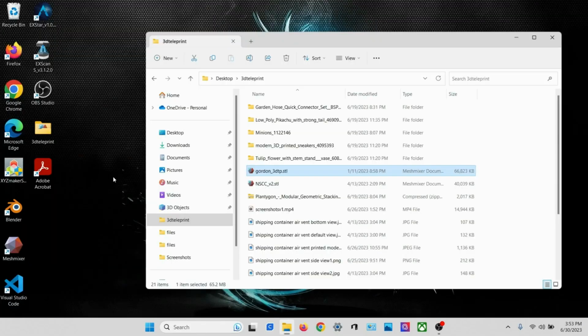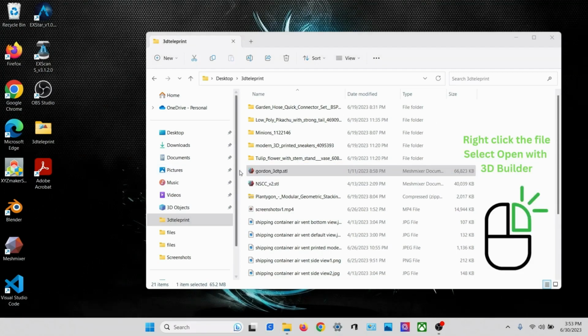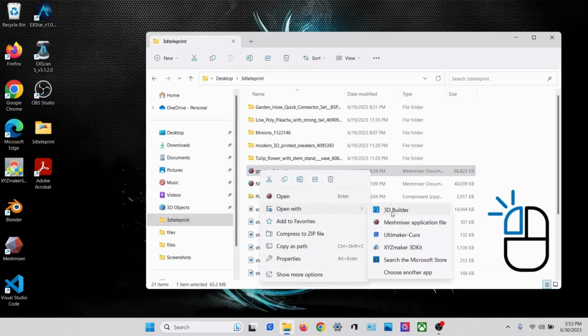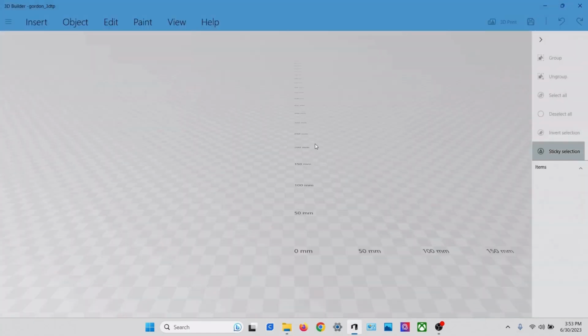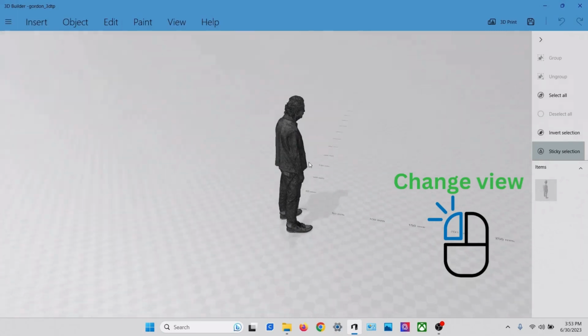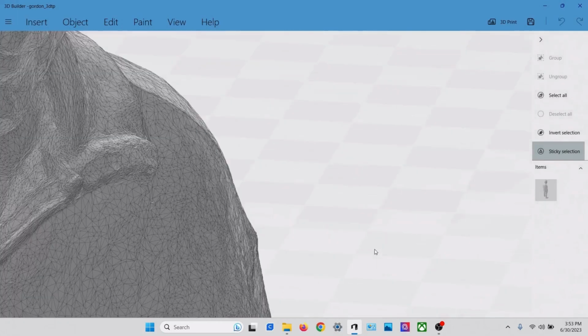3DTeleprint currently requires all uploaded STL files are under 50 megabytes in size. If your STL is over 50 megabytes in size, we can try the Simplify method to reduce its size. This object has a scan that has more than 1 million faces and is larger than the file size limit, so we need to reduce this object's density by reducing the amount of faces.